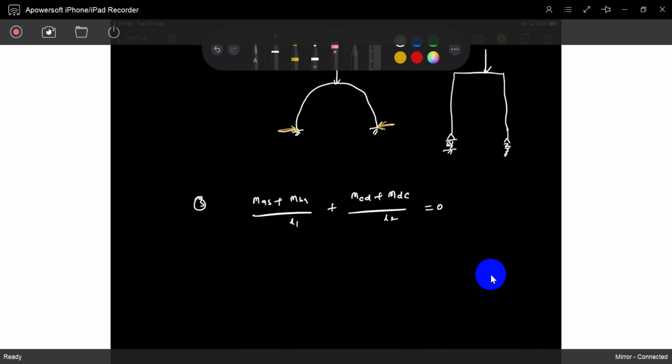I will give one suggestion. I didn't give any EI value, so EI theta B, EI theta C, and delta, which is also associated with EI, come up so many times that you have to write them down. So just take this value as X, this value as Y, this value as Z. You can treat it as a simple arithmetic problem and solve it easily, because every time you only have the 3 unknowns X, Y, Z.